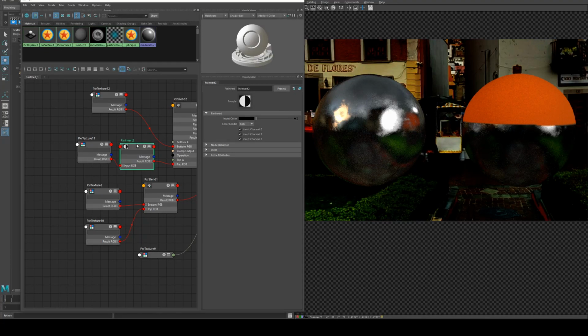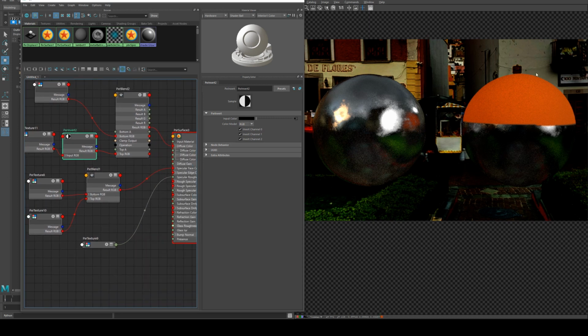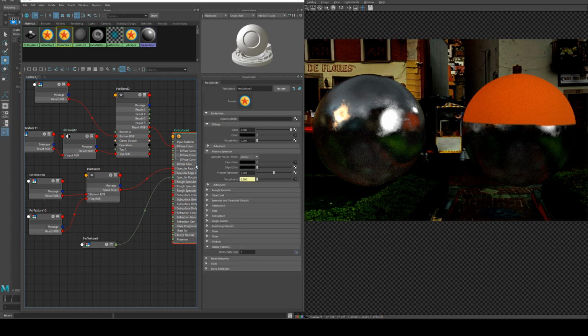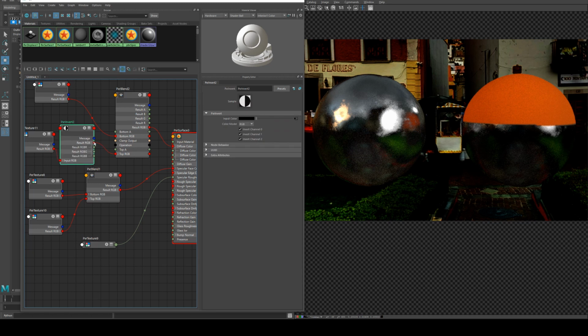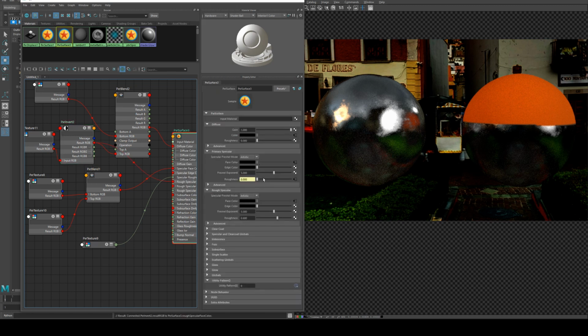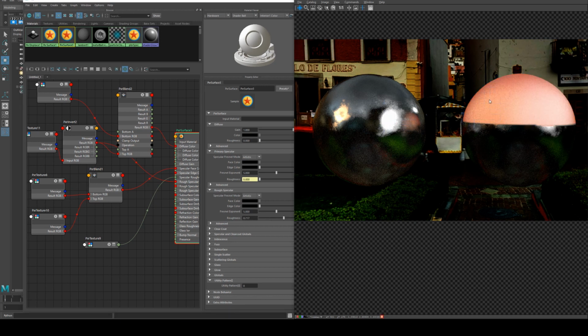Now because you have this mask, if you wanted to add any differences to this part of the map, for instance another amount, you wanted it to be specular rather than diffused. Now I only exported it as diffused. However, I could still make it specular by running this invert RGB into the rough specular face color, which will give us an extra input for specular. I could reduce the roughness there and run the IPR. And to show this a little bit better, I've just increased the roughness. And what we get here is a rough specular painted top, just by using that map there.